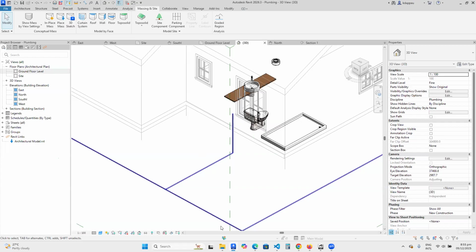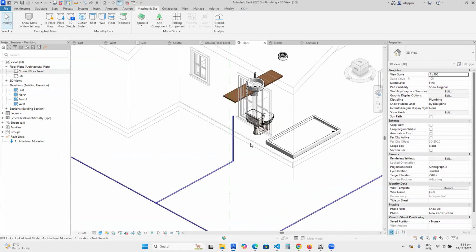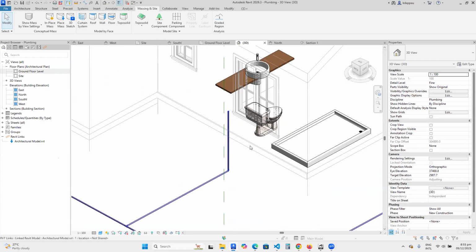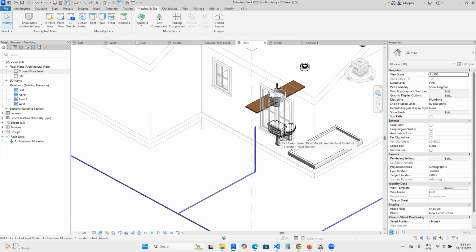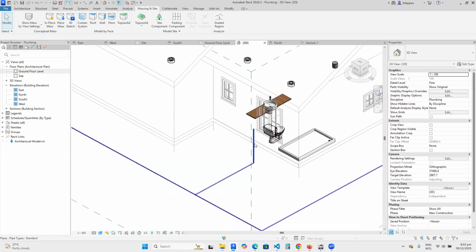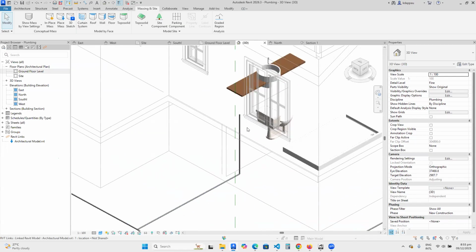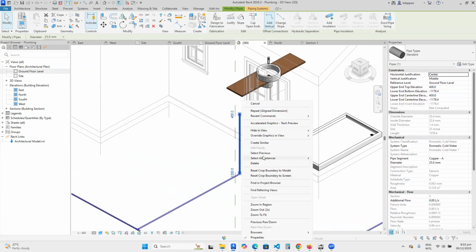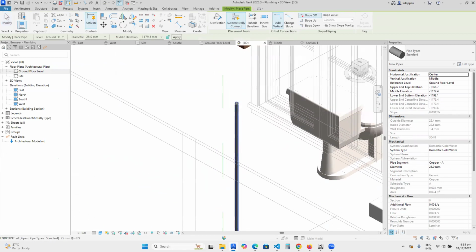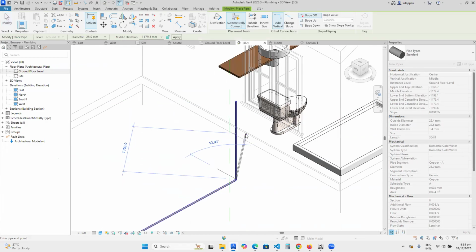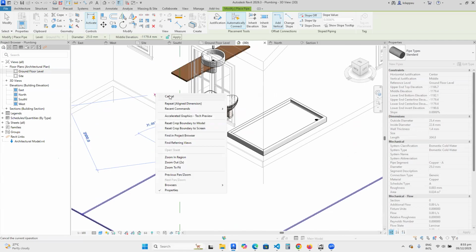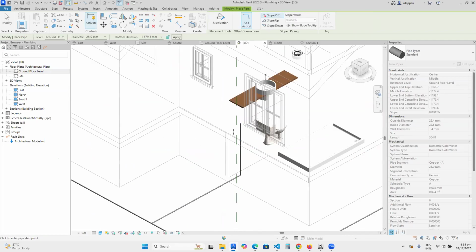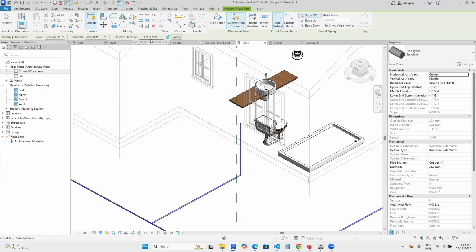No question. Now, when I bring the pipe up, I must then distribute it. I must connect some to the shower, connect some to the wash hand basin, and then connect it to the WC. So if I want to send some to the shower, I can come to a 3D, right click, create similar, select from the top here, move in this. You see the elevation is not specified. When I try to draw, it defaults to the elevation here.